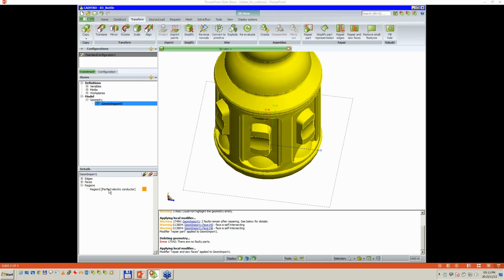Now, where it's also important to have a valid solid is, for example, when you use the MLFMM method. If you've used the method many times before, you may have noticed that sometimes it's difficult to get convergence for the solution. And one thing that we always suggest at support, and you'll also see in the Help Center, there's an article on the convergence of the FMM, how to improve it.